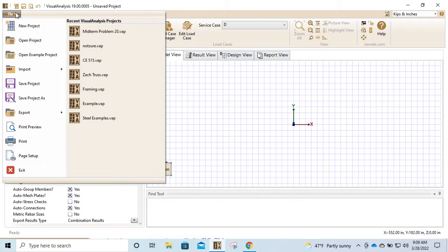So in Visual Analysis, for instance, when you're trying to pull in something from Revit, it's taking the analytical model. So what can happen, and it happens all the time to the point where it's not worth making this swap, okay, it's just worth modeling it on your own, in my opinion, or at least from my experience, is that there's problems with the analytical model from your physical model. And when it comes into Visual Analysis, nodes are off. So you got beams that are at an angle, things are oriented with respect to the grids, all because of those differences between the Revit physical model and then the analytical model that's done. And then VA pulling it in here. Okay.